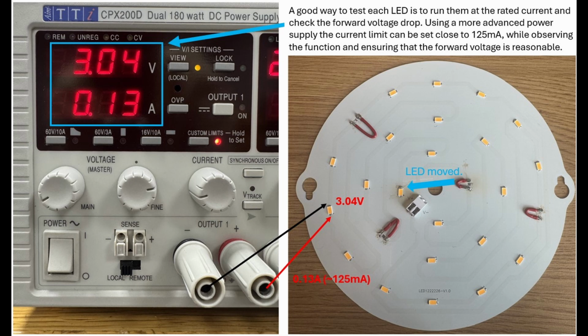For one of these LEDs, I made a jumper over it to close the circuit. But since I need a balance in the current sharing, I had to move one of the good LEDs from one side to the other leg to make sure I have the same number of LEDs on each leg. So now I end up with 11 instead of 13 on each side.